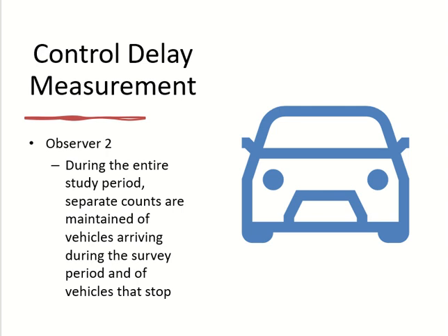Alright? There is no time interval for him. There is no integral, multiple and anything. Okay? Whenever a vehicle comes, he will count, and his time finishes when the survey is done. 10 minutes means 10 minutes. He doesn't have to wait for these vehicles to go as well. Clear? Okay? So, now keep in mind, 2 guys: one is taking the queue, the other one is taking vehicles arrived and stopped. Before you start the study, find out the free flow speed and make sure the queue is not too long. Clear?